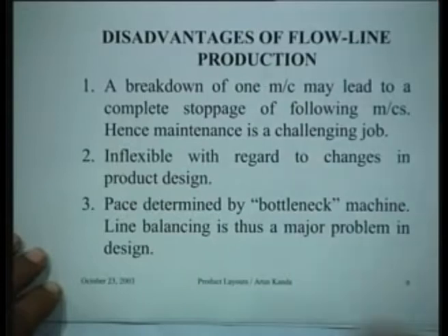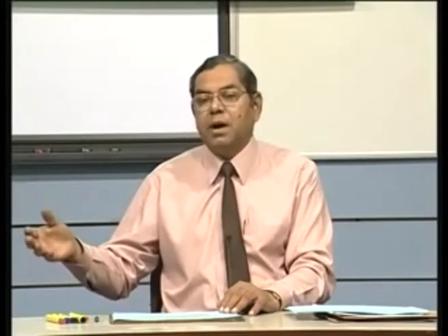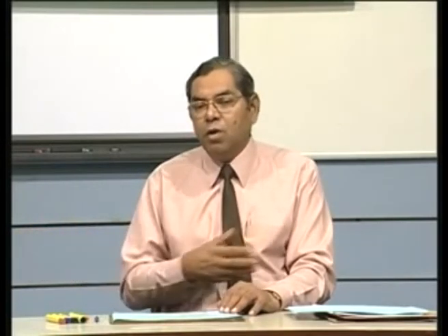Obviously, if different operations, workstations take different amounts of time to process the part, the overall pace of the line will be determined by the slowest machine, and therefore you would like to have, as far as possible, fairly constant times for all the sections, all the workstations. This may not be possible for various reasons, but at least that's the intention.